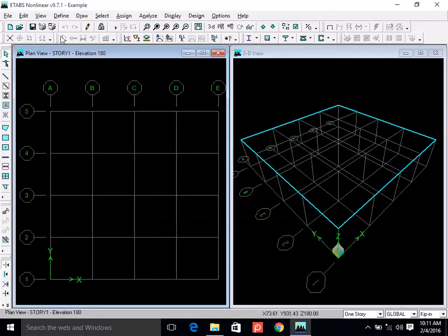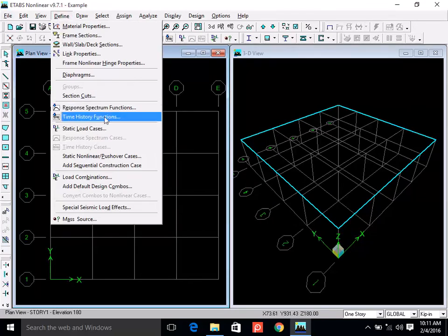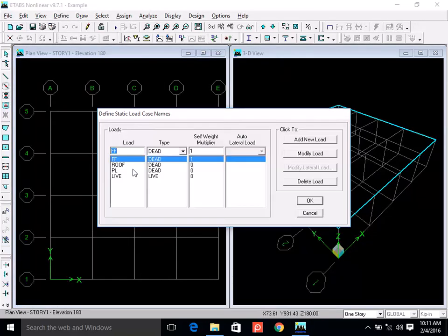So after that, we defined static load cases, and they were dead loads. We defined 3 types of dead load: floor finishes, roof details, partition. And we said that out of these 3, we can have self-weight multiplier 1 for only one of them, so that self-weight would be calculated and added to the dead load. And we also defined live load with self-weight multiplier, of course, 0. We postponed defining earthquake and wind loads because you have not studied earthquake.